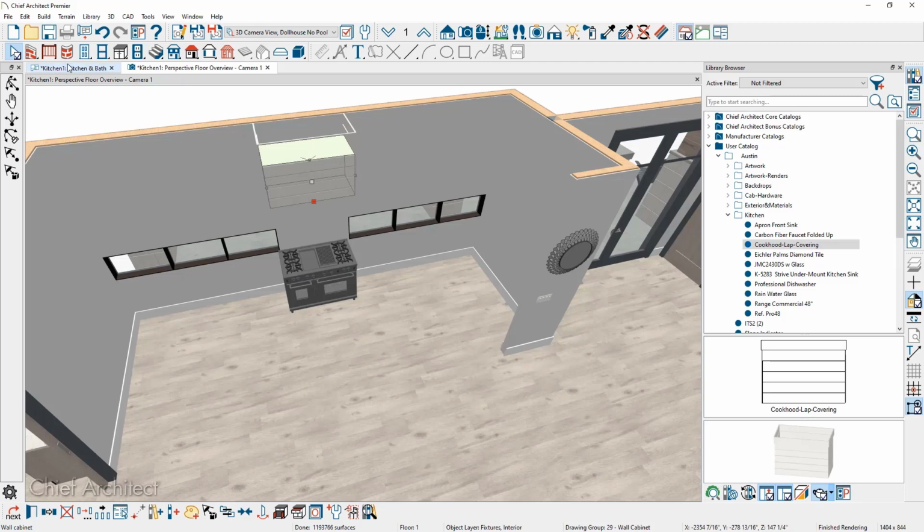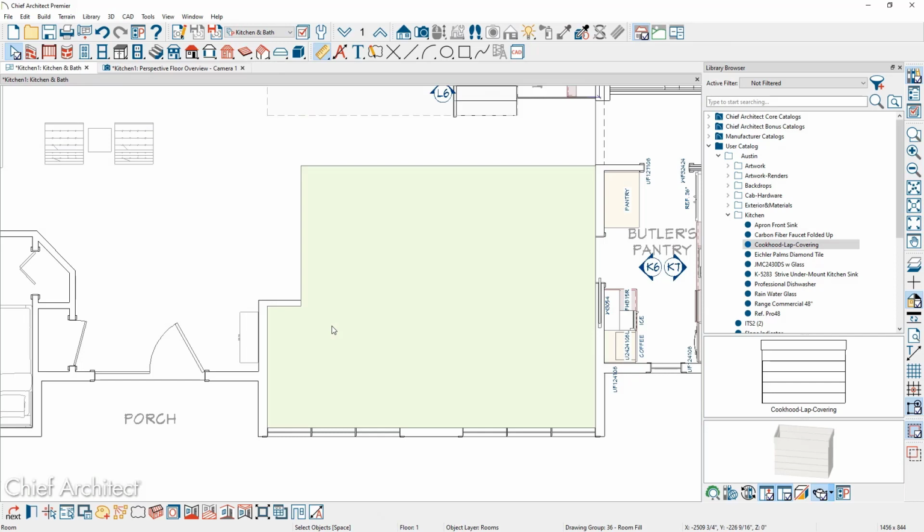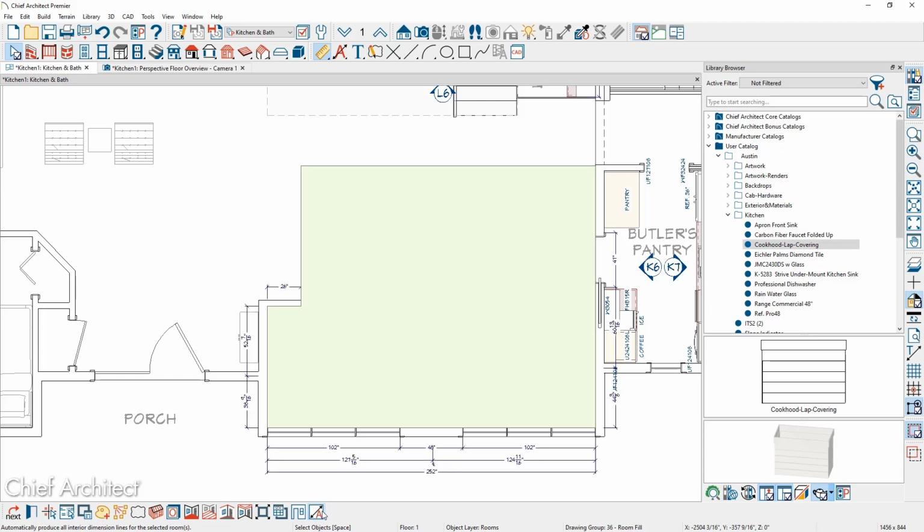And when I go back over into the plan view and I click inside the room, you see room definition. There are some invisible walls surrounding the room; I don't have that layer turned on. In the lower edit menu is the tool to place the automatic room dimensions. If you're using X13 and prior, you'll see another tool called the Auto NKBA dimensions. That's the best tool to use when you're using those versions and older.